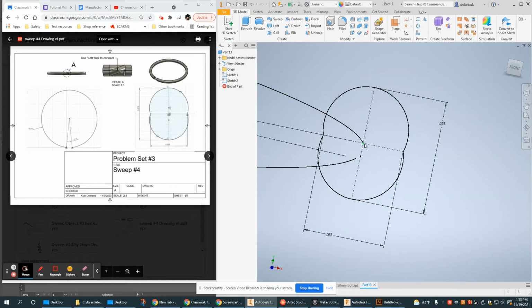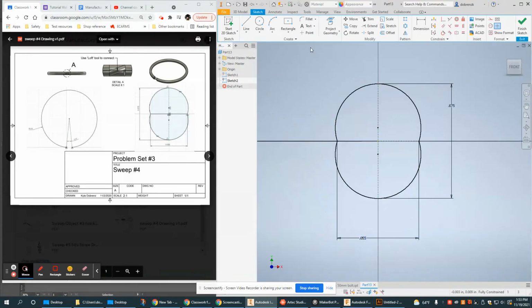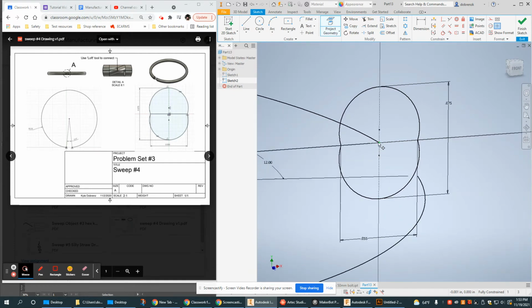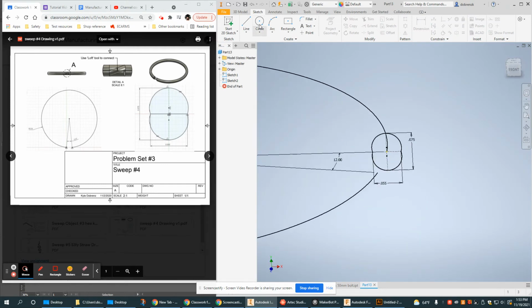Now remember, if you did not use an origin plane, you need to import this endpoint. There has to be a point shared between these two different sketches. And how do you do that? Well, in the second sketch, which I need to reopen here, you can use the project tool and take that point from the first sketch. If you use the origin like I did, you don't have to do that. The origin exists in all planes unless you go and delete it or something. But if you did not use an origin plane, then that is a crucial step.